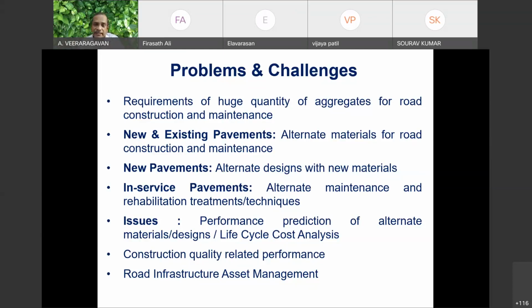What I mean here is that these pavements with a CBR of 4 to 10 and 10 to 20 CBRs will perform differently, and will warrant maintenance at different times. One may warrant maintenance in the 4th year, the 8th year, and the 12th year. Second may warrant maintenance in the 7th year and the 14th year. Third design may warrant maintenance only in the 10th year. So you do the maintenance in different years.